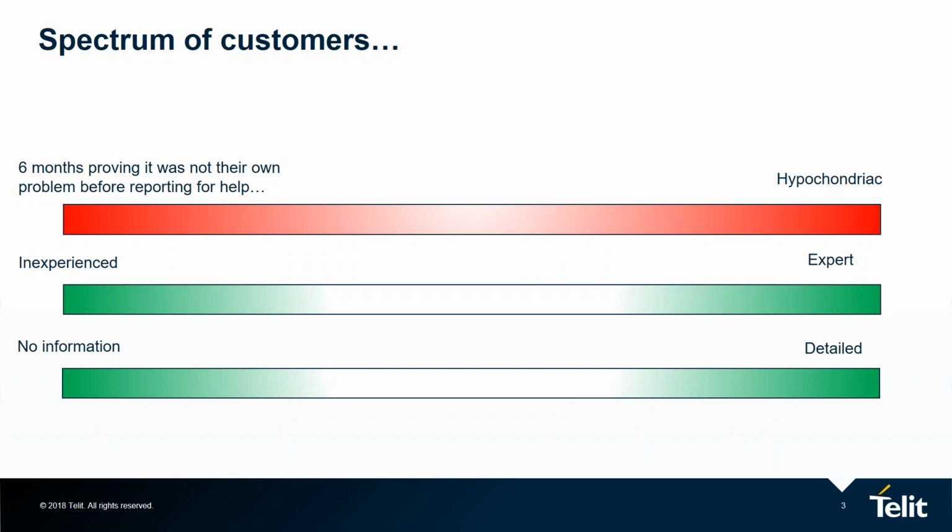From experience, I can say we went back and forth, email after email, trying to figure out why a customer was unable to register his modem. In the end, he's convinced it's broken, it's not working, he has a faulty unit. We can exchange emails for several hours. In one case, I remember having, in the end, a photograph back of the setup. It was very quick to spot that the antenna was not plugged into the main antenna port, but into the diversity port.